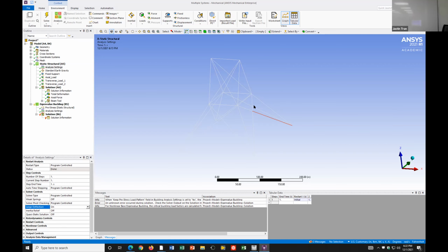If you look at the first deformation, you can see it's only failing with one leg. Someone asked me this one too. If you actually apply the loads, it's not that you're going to see no deformation everywhere else. It's just that the only one that's going to fail is that member. The shape you're viewing is telling you this part only is going to buckle. If you apply that load onto your static structure, you're going to see deformation everywhere, but the only one that's going to buckle is this one. So at this multiplier, there's a chance that this structure might live, if the safety factor is good enough.